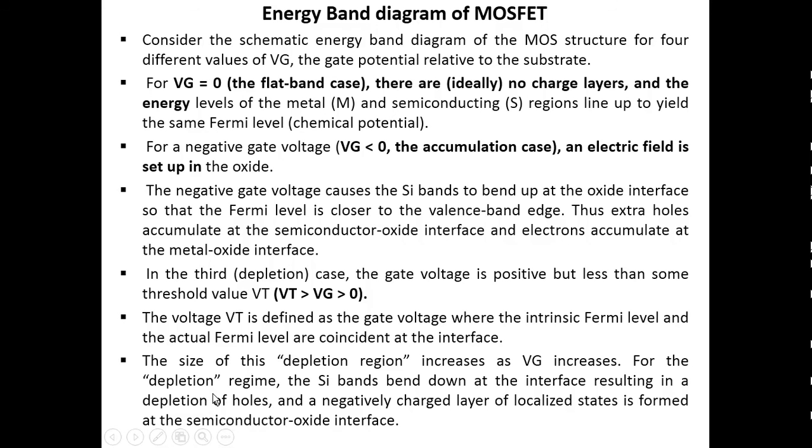Initially, of course, that will be due to the positive voltage applied between the drain and source. When the positive voltage is applied between the drain and source, what happens? Since the drain is connected to a heavily doped n-type material and it is connected to positive, between the substrate and the n-type drain there is a reverse potential, isn't it? There is a reverse biasing.